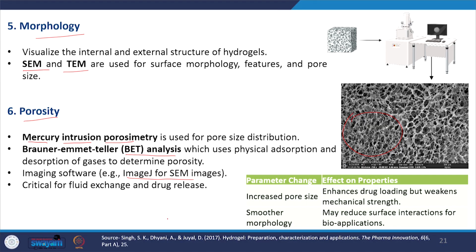The porosity is one of the important parameters for fluid exchange and drug release. Based on the porosity, the drug release can be slow or it can be faster. So that's why the porosity is a very important parameter. If we have an increased pore size, it enhances the drug loading, but it weakens the mechanical strength. And if you have a smoother morphology, it may reduce the surface interaction for bio applications.